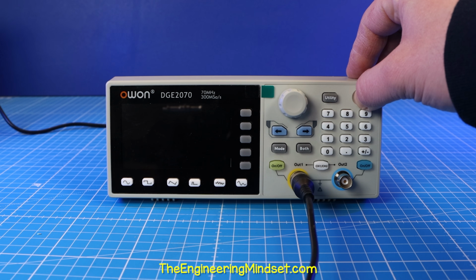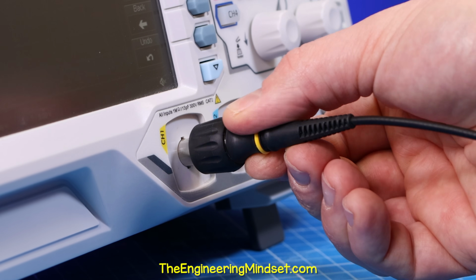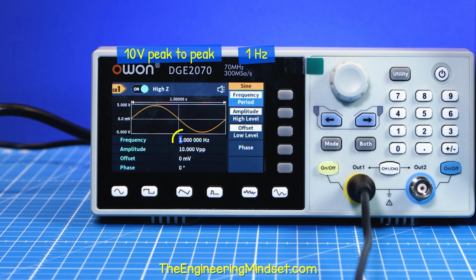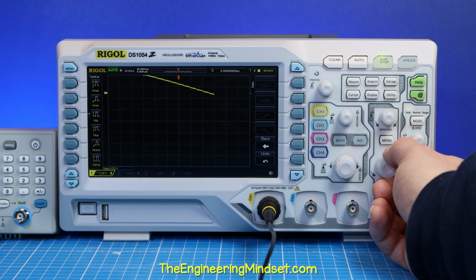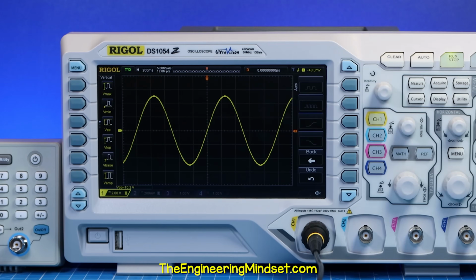For the remaining examples, I'm going to use the signal generator, which is safer. Connect channel 1 to the signal generator and apply a 10-volt peak-to-peak 1 Hz sine wave. Press Auto and notice the oscilloscope can't find the signal because it's too slow. Manually adjust the scale to 2 volts and 200 milliseconds per division. Then change the position to see that signal clearly.